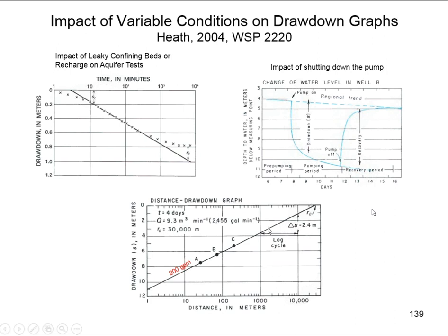So to get that, I'll take 2 points here, 4. Now take half of that, and 8 comes to 4, and I can draw in my 100 gallon per minute pumping rate, and I get less than a meter of drawdown.